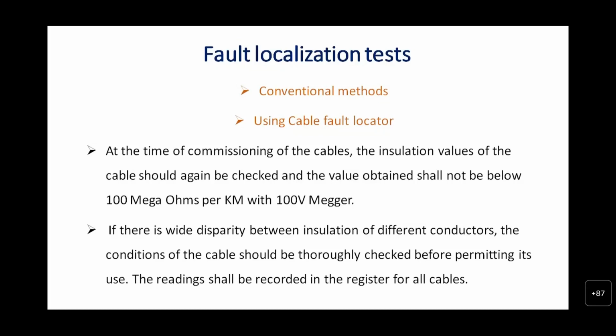In the conventional methods, people find out whether the integrity of the cable is there or not by checking from the station whether the nearest LC gate phone is working or not, whether the IB phone is working or not, or they will put the EC point and find out how the communication is between the ECs.